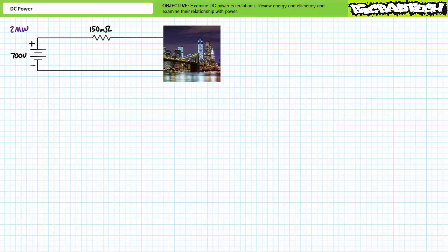This might not seem like much resistance, and you may instinctively presume that the line losses will be minimal. However, this is far from the truth. I must remind you that power is equal to current squared times resistance. Even a small resistance carrying large amounts of current will dissipate tremendous amounts of power. In this case, any power dissipated by the transmission line would be considered a loss.